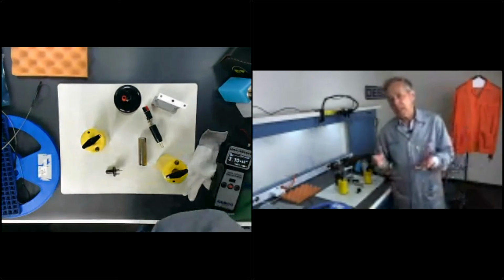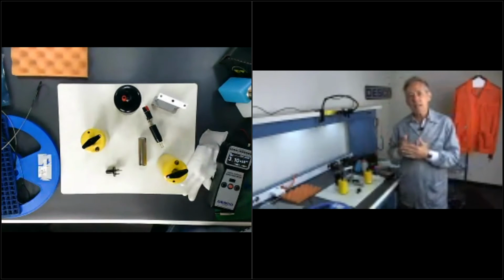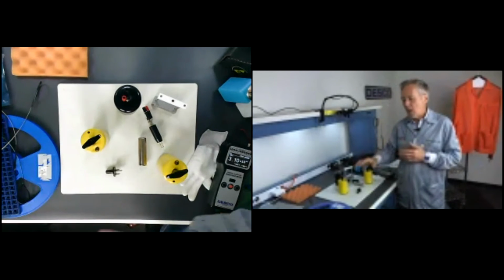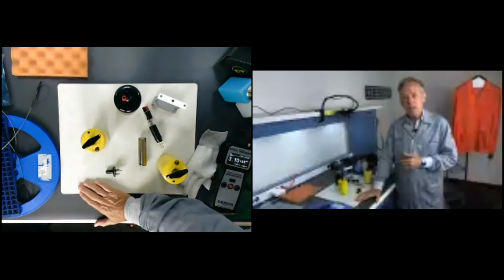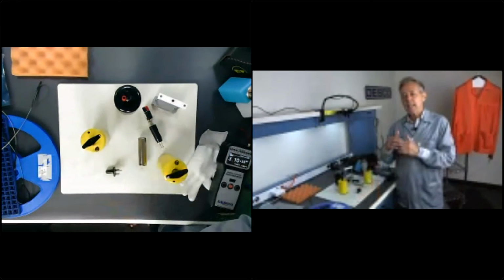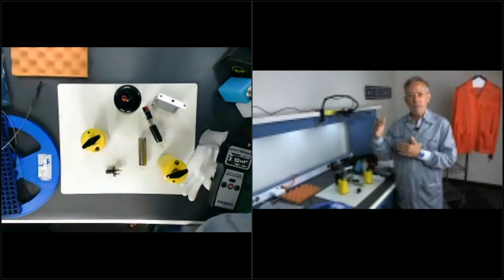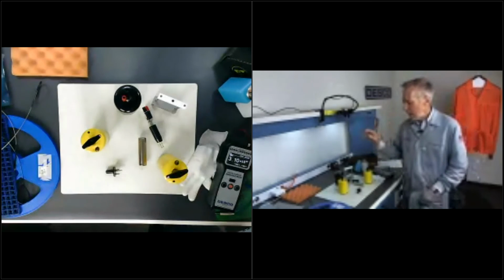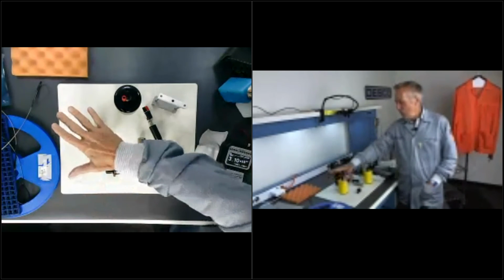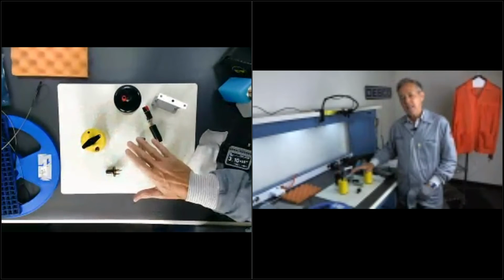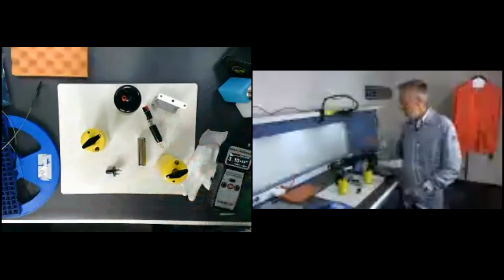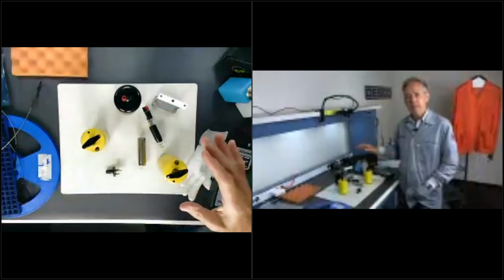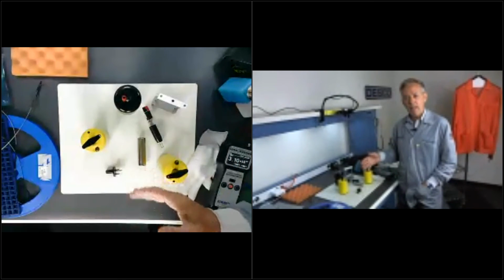Yes, well, obviously contamination, dirt, or any type of insulative layer that's on an ESD work surface, floor, or anything else in our EPA, that contamination or dust and dirt over time is going to affect the resistance of the material. However, when it comes to compliance verification, we want to test it as is. So if I test my mat and it's got flux residue all over it, or I test my floor and it's filthy and it's in spec, great.